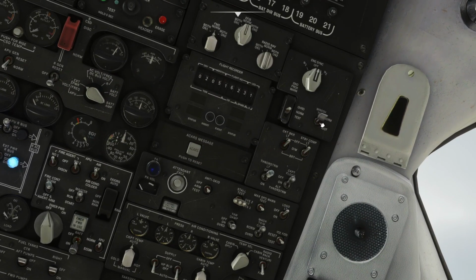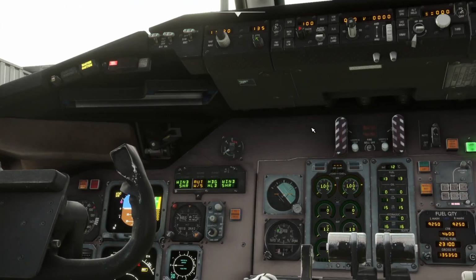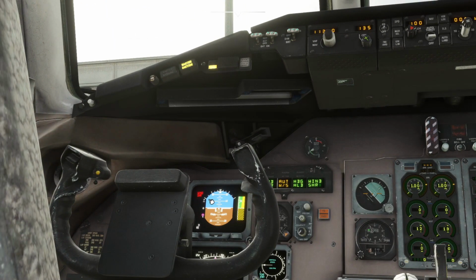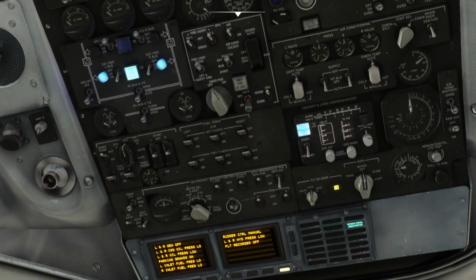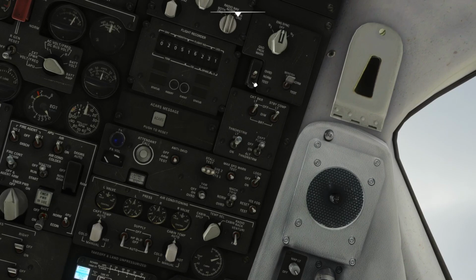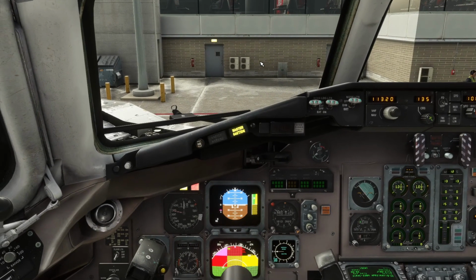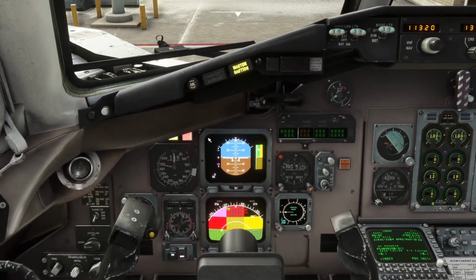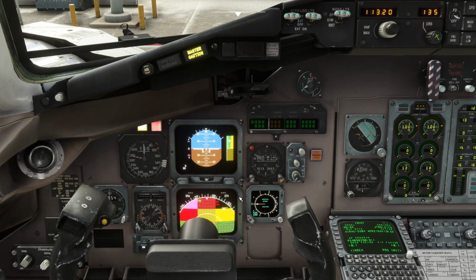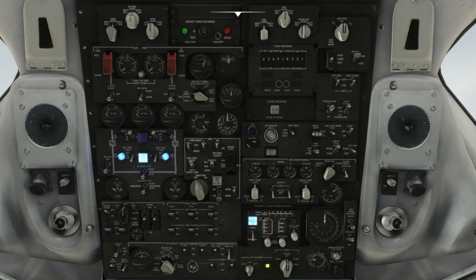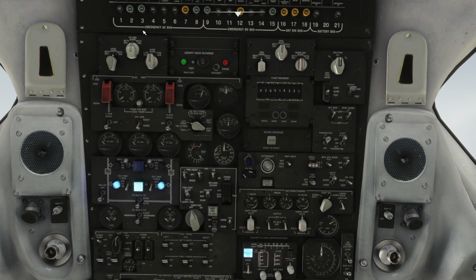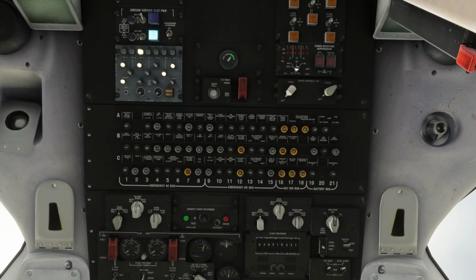We can test the wind shear. We're looking for that and the PFD indication. Very good. And the ground proximity test. This is the longest of all of them, I think. I'll show you what that's like. So it'll show a couple warnings down here and test the terrain system on the ND there. I believe that's what it does. And these all need to be facing up. This is just like different system sources, selectors. Okay, so that's the overhead done.